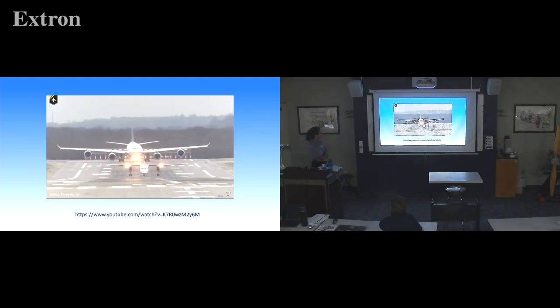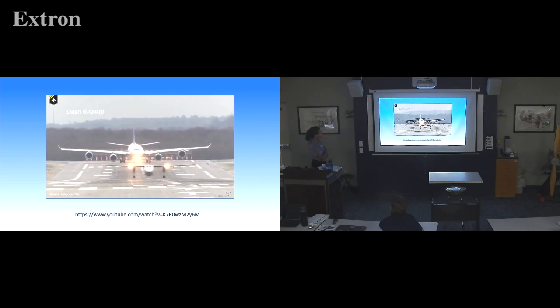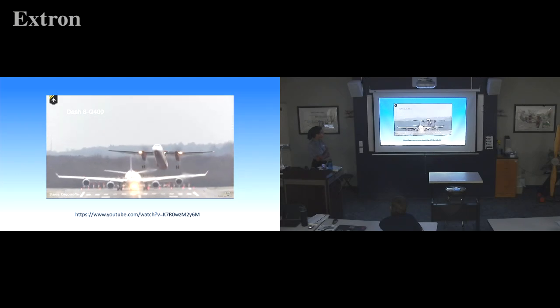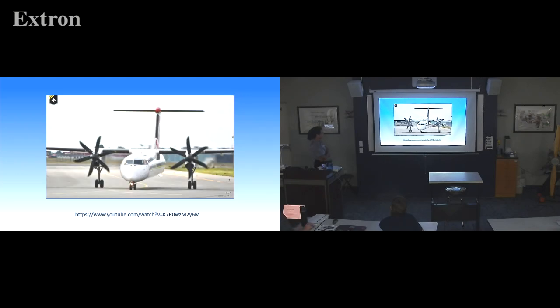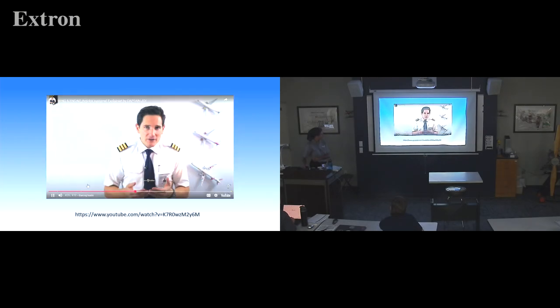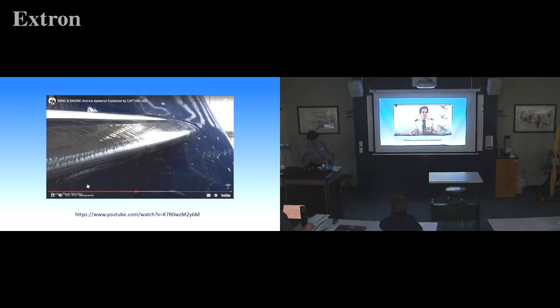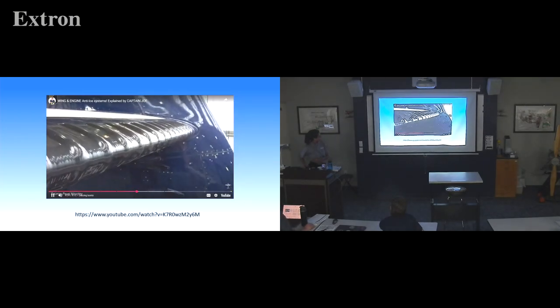Now let's look at other anti-icing systems. Turboprop planes like the Dash 8 Q400, for example, are fitted with the so-called de-icing boots system, which is also based on bleed air supply extracted from the engines, and you can easily recognize these planes fitted with the pneumatic boot system as their leading edges come with a black rubber coating. And once you have visible indication of ice, you actually wait a few minutes to let the ice build up a few layers.